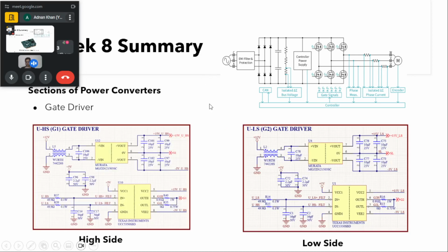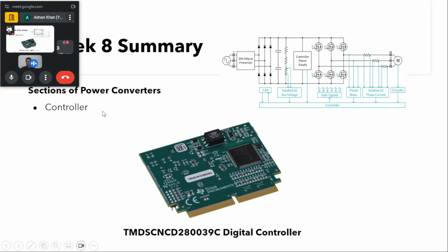Now the other thing is the controller. The controller in a particular converter can be mainly a digital controller or an analog controller. In the analog part we can have some ICs formed of some op amps, which will be taking the appropriate voltages and currents, and which will then provide the subsequent control action and provide the pulses for our devices.